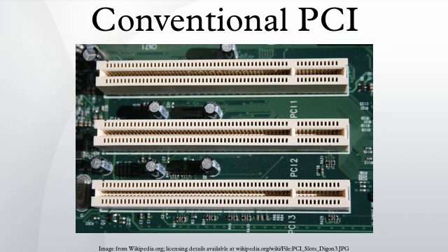If the address requires 64 bits, a dual address cycle is still required, but the high half of the bus carries the upper half of the address and the final command code during both address phase cycles. This allows a 64-bit target to see the entire address and begin responding earlier.